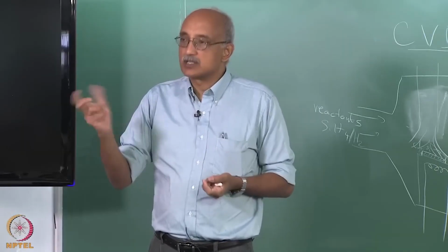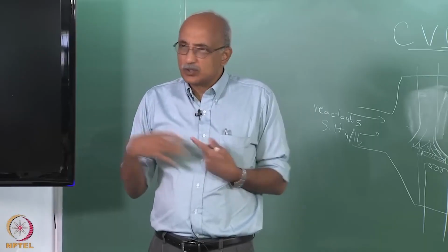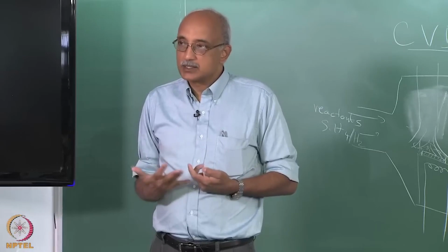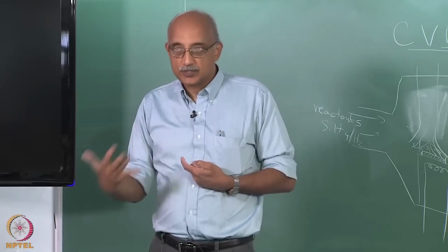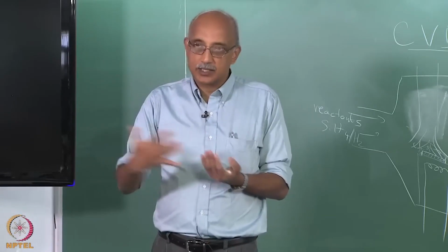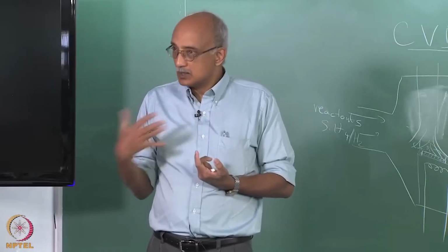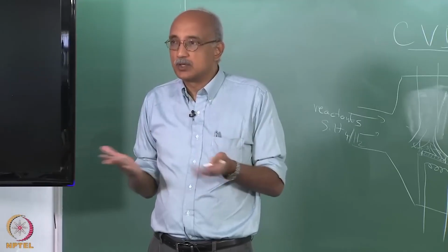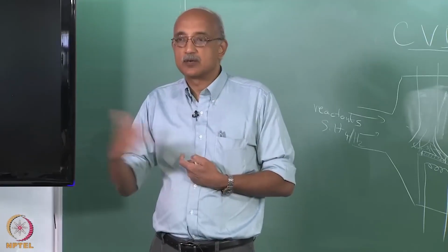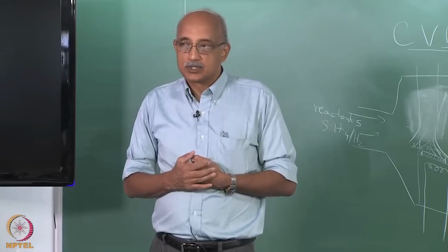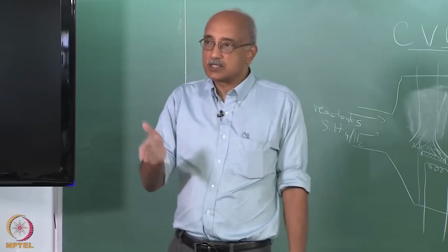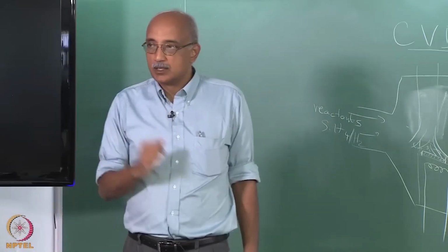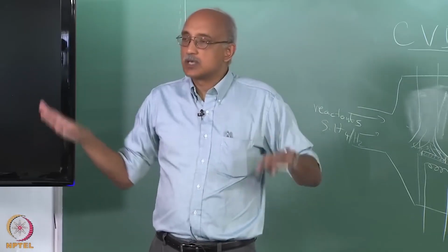It is kind of the reverse of stagnation flows, right? Why don't you want stagnation flow? Again, stagnation essentially implies that there is more time for deposition to happen, the reactants stay in contact with the substrate for a longer period of time. So, it is all goodness, but then you cannot control it. Once stagnation happens, you cannot break it essentially. So, you cannot have a sharp cutoff and say that here is where I want to stop, as soon as my thickness reaches this number I want to stop here. So, you really do not want the two extremes.